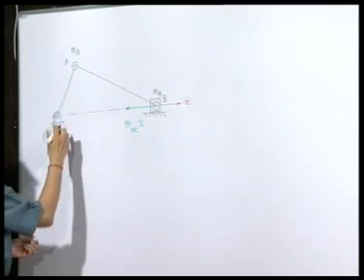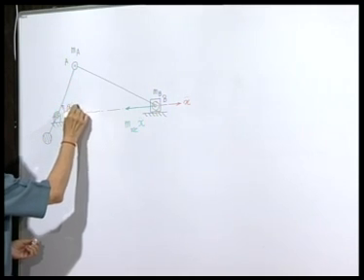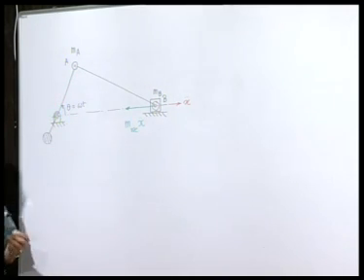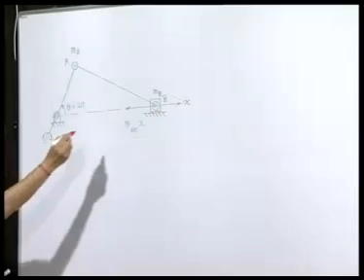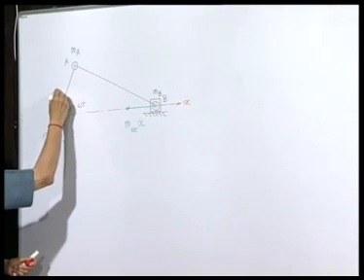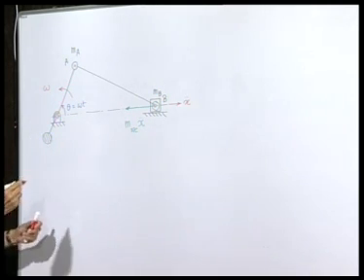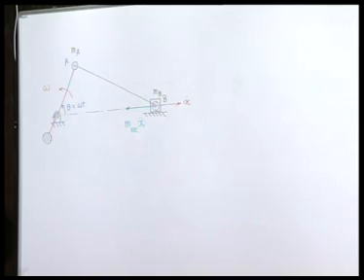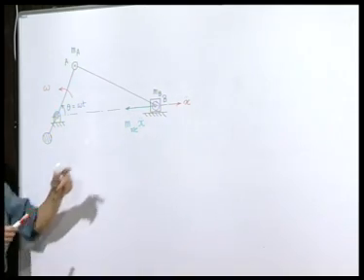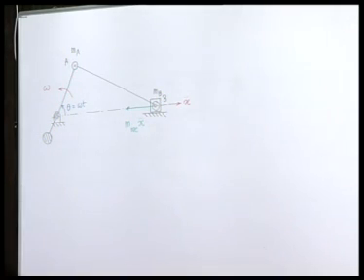It is obviously simple to look at and much simpler to handle, but even then we should not forget that the expression for x 2 dot itself is again an infinite series, and even for a smooth operation where the crank rotates at a constant angular velocity, the x 2 dot will be an infinite series containing all the higher harmonics.